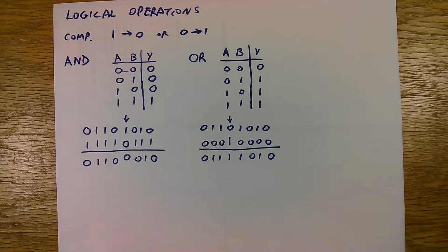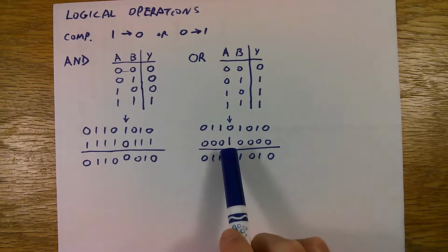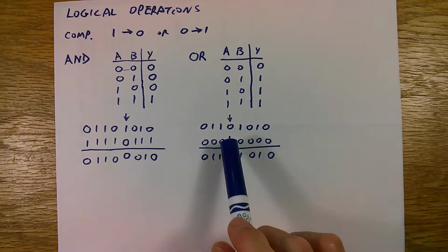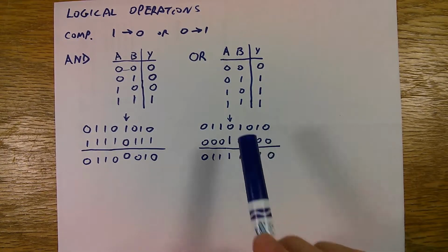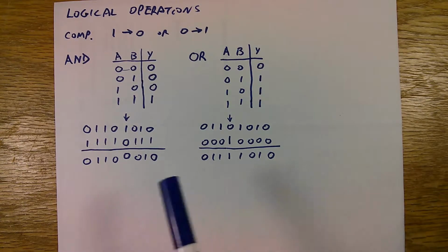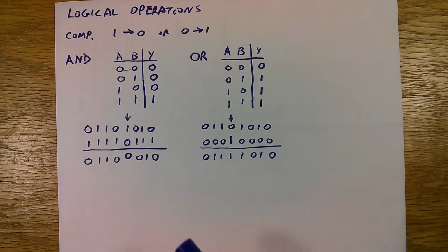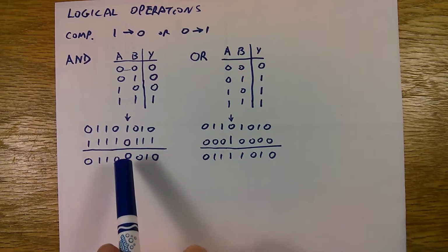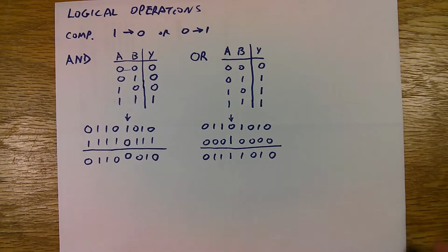If you remember my tutorial on the control of the I/O bits by directly accessing the I/O ports, those are 8-bit ports. Each bit represents one of the pins on the microprocessor. If I wanted to set a particular pin on the microprocessor, I just OR it with this number here, with the 1 bit wherever I want to set that particular I/O pin high. Or if I want to clear that I/O pin, make it low, I AND it with this number here, making the 0 in the bit that I want to make low.